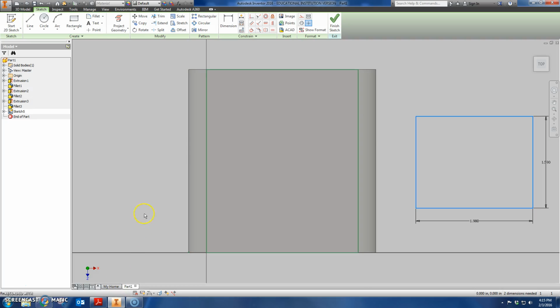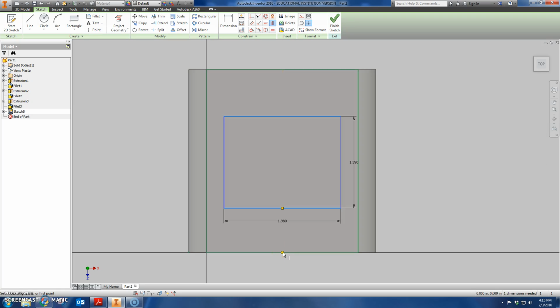Well, that's really simple on Autodesk Inventor. All I need to do is say, okay, vertically, I'm going to align this middle point here, and you can see that red dotted line appear just like in the first video, and I need to align it with the midpoint of this line, which is right here. And I click, and it's halfway in between. So I don't need the 0.60. And that's good because it's not actually correct anyway. It's a little bit off from that, okay? So I have it in place, left to right.